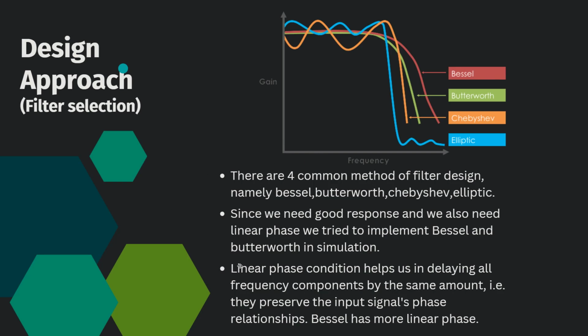when we transmit in the channel. And coming to the simulation, we also calculated the distortion analysis, which shows us how much our signal is distorted after the transmission. So for the second order Bessel we got around 1.08%, and for the third order Bessel we got around 1.57% in the distortion, and the distortion curve is attached at the right side of the image.